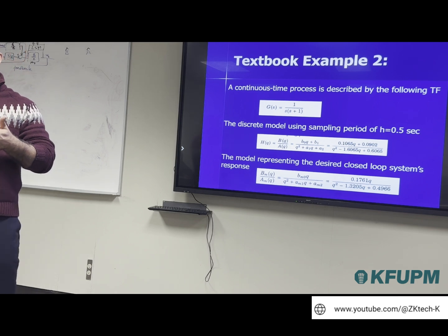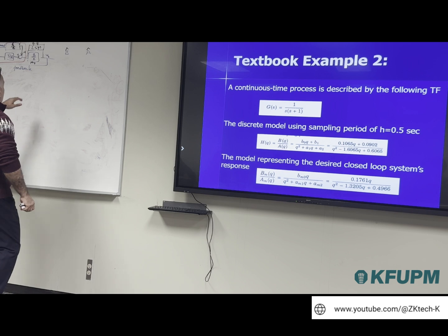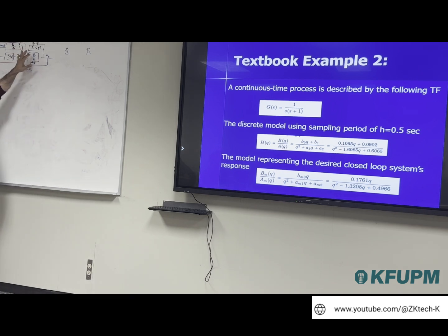If you assume that the system will go to 95% of its output, so 3 time constants, then you are going to get 6 points. And this is really not that much. It works, but not that much. Normally, you have to target the frequency that will give you enough points. But you cannot target a frequency that is very, very fast, which means h very, very small, because at that time you are going to make your system completely busy with making the identification and trying to find the value of the parameters. So there is kind of a compromise. Trade-off. This point clear? All right.